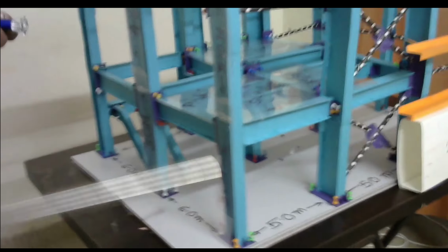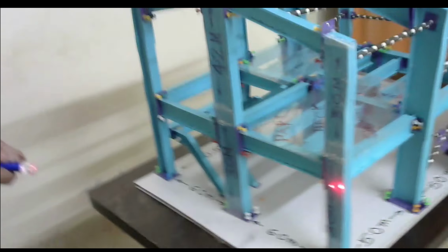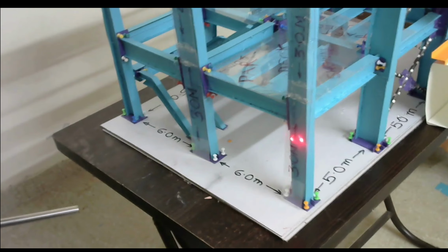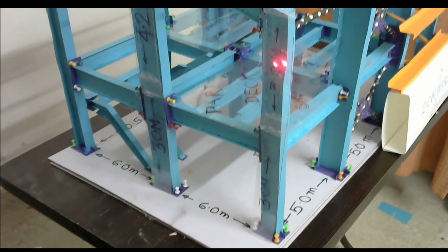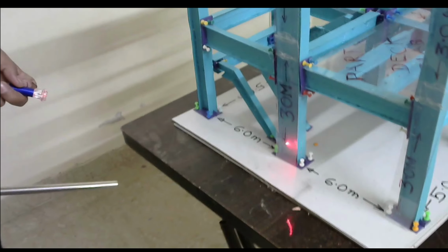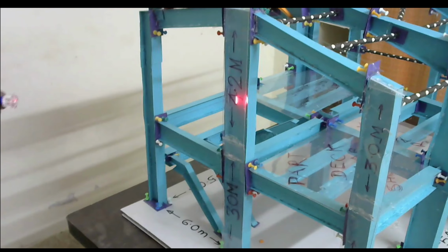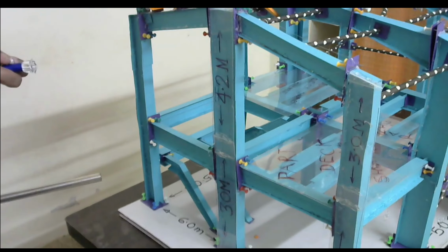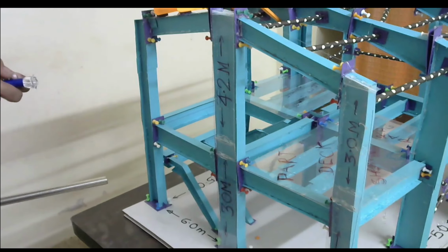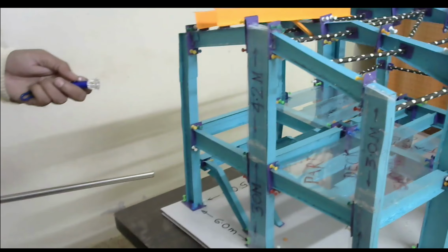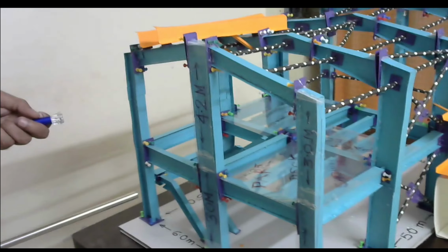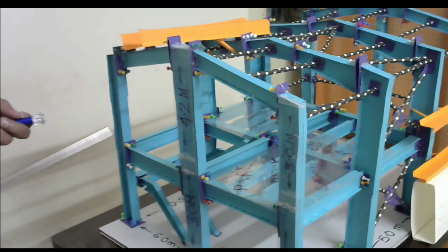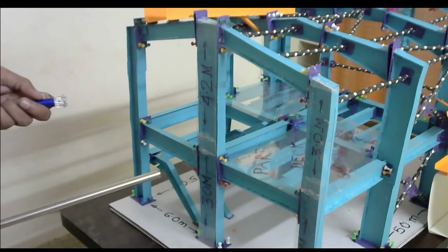So let us come to the gable end again. You can see the center to center height of the column beam intersection is 3 meter for the first floor. Then up to the hip, it is 3 meter. Then at the ridge, again the bottom is still 3 meter, and the height of the ridge to the center point is 4 meter. So these center to center distances we should remember, because when we start defining the effective length parameters, we will have to multiply this center to center distance to arrive at the effective length parameter.